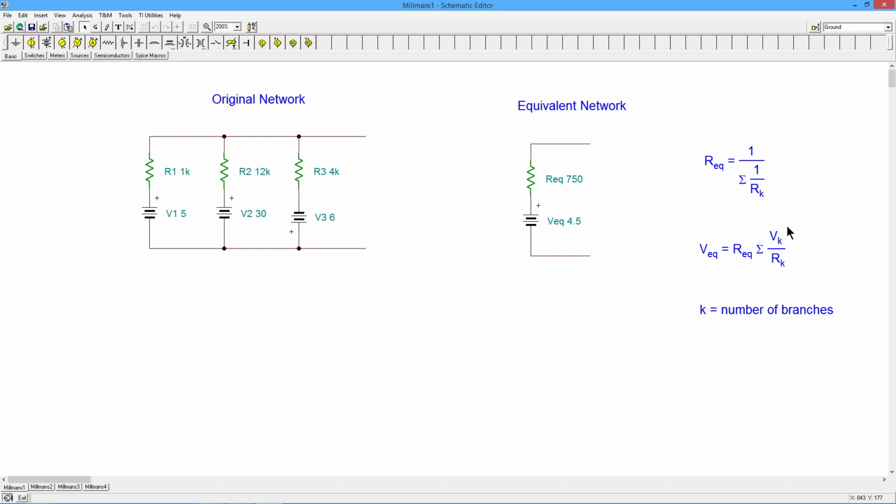All right. Okay, now, first of all, this should not be alarming in any way, because after all, you could always use Thevenin's theorem, right? Thevenin's theorem says you can take a network like this and turn it into a Thevenin equivalent. In other words, Veq would be the Vthev, and Req would be the Rthev. So that's by itself not all that crazy. This is kind of a nice compact way of writing the formula, though, unlike trying to go through with Thevenin's theorem. Depending on how you attack Thevenin's theorem, this might be a little bit of work.